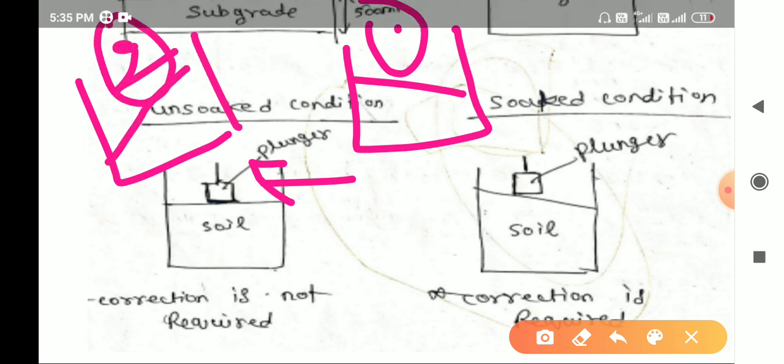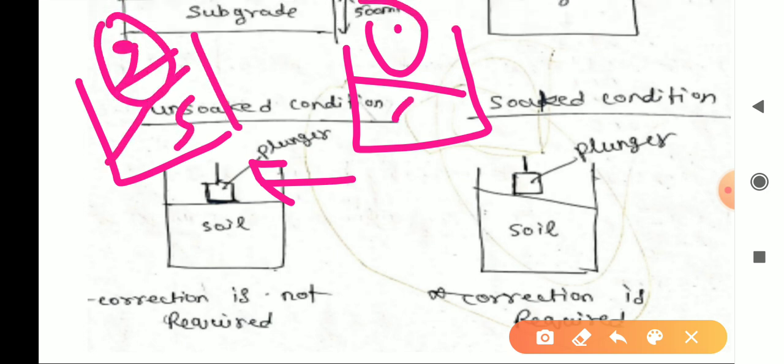Why is it like this? The soil used for testing contains more black cotton soil, which means it is highly expansive. Once it is expansive, sudden volume changes occur.